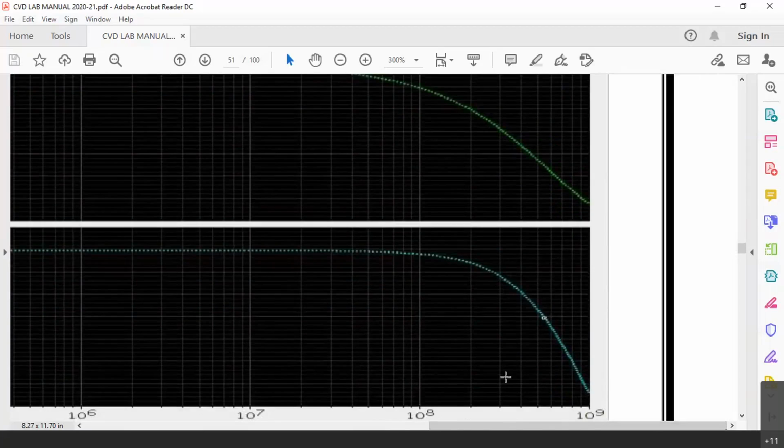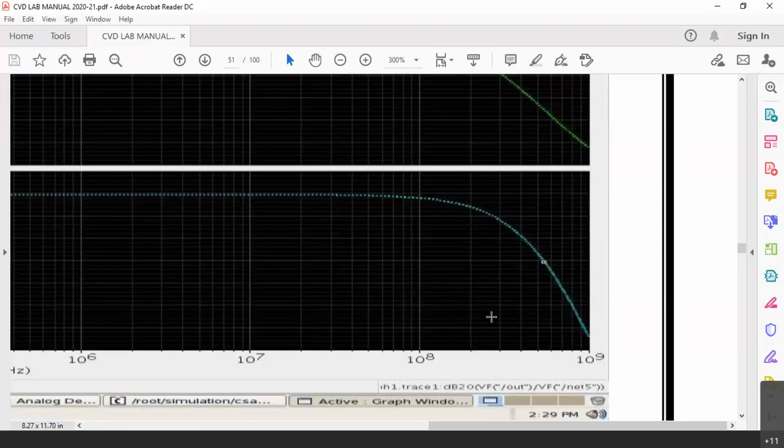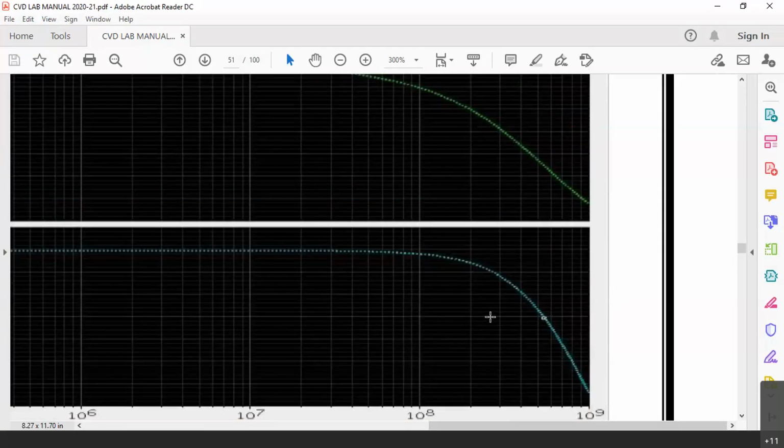When the output equals input, the gain is unity. When the gain is unity, in decibels, the gain is 0 dB. So the Nyquist criterion, invented by Nyquist himself, says that in the complex plane, 0 dB and 0 degree should not coincide. That is how gain margin and phase margin are defined.